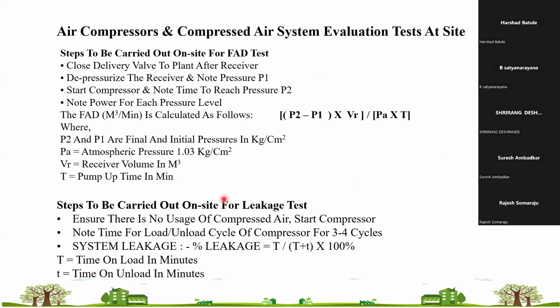Compressor displacement is calculated as pi by 4 D square into L into S into X into N, the number of cylinders. D is your cylinder bore. You need to go through those formulas in your book once, but majorly isothermal efficiency is asked in the 5-mark numericals, not the volumetric efficiency.